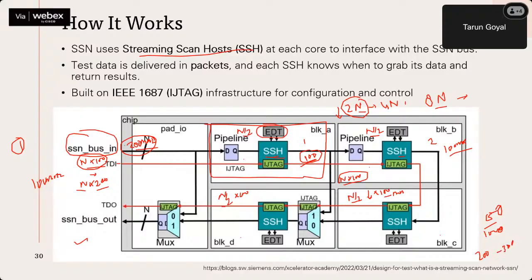So it's just an example of four cores where we are targeting. When we are targeting this kind of design, then we can assume thousands, 5,000 kind of IO requirement if we keep doing that. We stopped doing this. What we started doing is, whatever the IOs are, usually in the range of 100 plus or minus 50, we consume these IOs, and we have the same number of IOs. We bring the data in faster and run the cores slower.